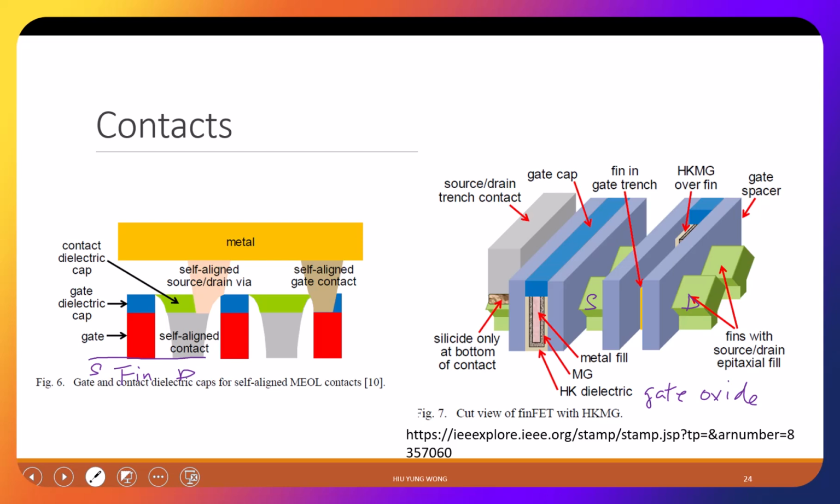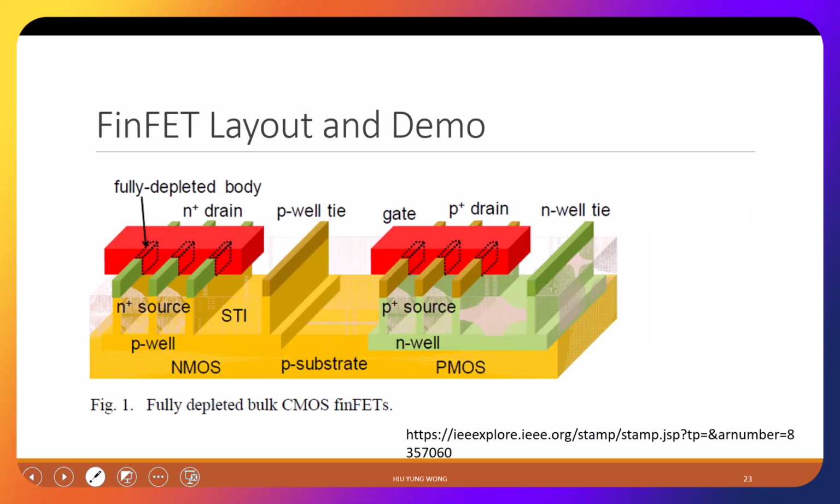The previous slide, you had the substrate. So that P-well is short substrate, right? So if you bias the P-well tie, you bias the substrate. This is just like a regular bulk CMOS, not triple well, right? Your P-well, you are tied, you bias all the P-well and P substrate. But then here N-well, you bias by the N-well tie, right? So you probably will bias this at 1 volt, this bias at 0 volt, right? Now I go to 1 volt instead of 5 volt because FinFET are using something lower than that, or even 0.8 for 14 nanometer.